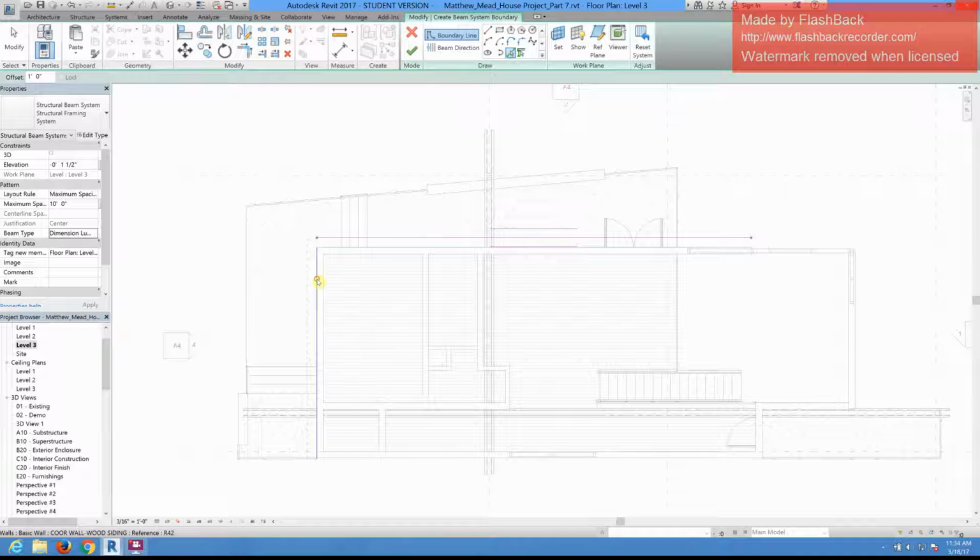Okay, so I'm going to highlight 1 foot all the way around all of my exterior walls. You should be able to see the pink line though, right? Yeah, we can. All right, so you should have an understanding. We all know this project well enough that you know what I'm clicking on. All right, so we're going to close the boundary. Make sure this is one consistent boundary all the way around. All right, that looks good.